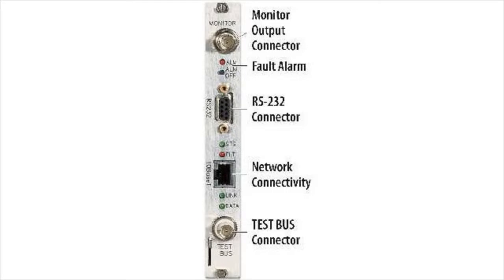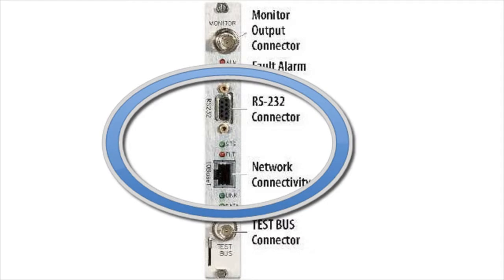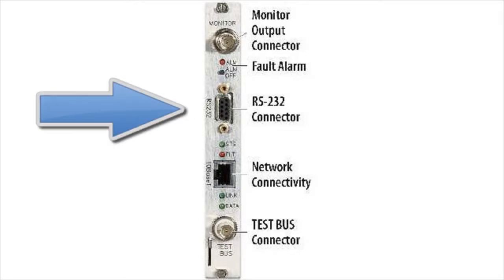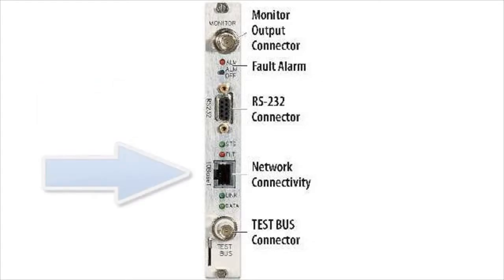The 28000 system interfaces to a host PC through a direct connection or network using the 28000 BIF control card. The serial or Ethernet interface cables are connected to the 28000 BIF control card. The serial option provides a communication link using RS-232 format. The Ethernet interface can be configured to provide a link to the mainframe using a local or network connection with static or dynamic IP addressing.